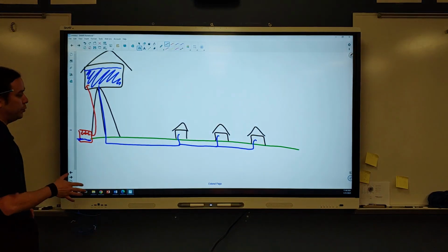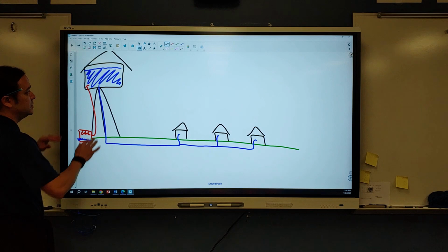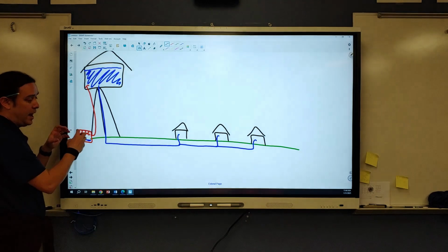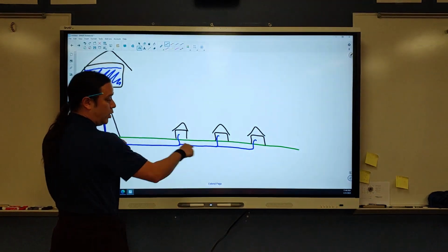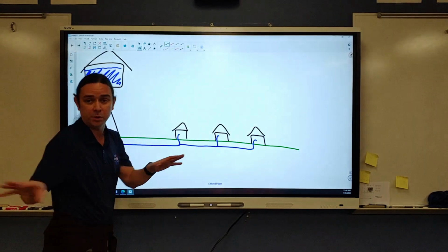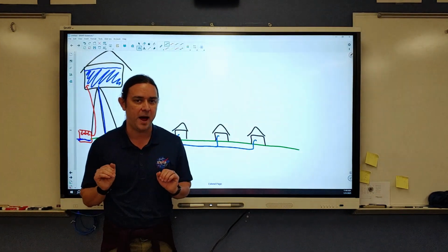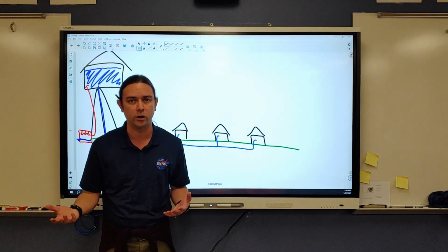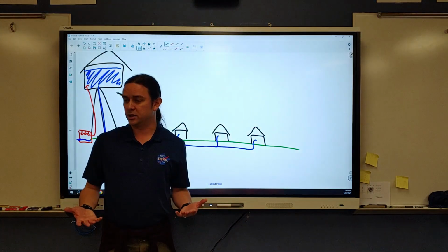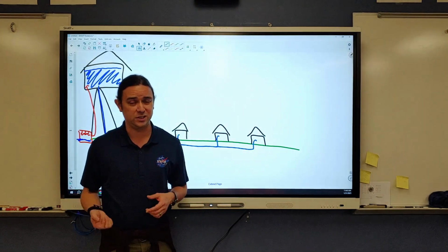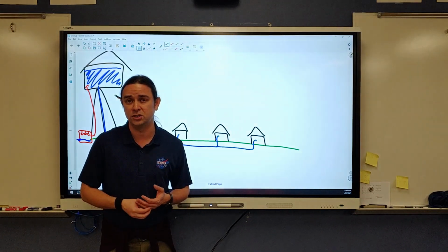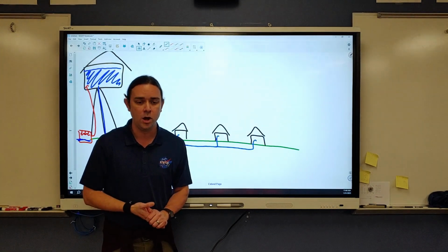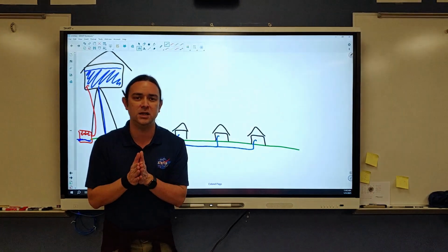And so one of the ways that you could do things, and a lot of people might not necessarily realize this, ignore the possibility of a water tower and think about having just a pump. Well, we could have a high-powered pump that was actually pressurizing our entire water system, and therefore it would supply all the things that we need. Except what happens if we have a power outage? Well, if the power goes out, then the pump goes off, and we also lose water. Well, think about that. If you've ever been in a situation where the power has gone out, usually the sink and the toilets and all the water systems usually still work. Now, your water heater may turn off because it might rely on electrical power of some kind or another, but you still have water, and that's actually by design.